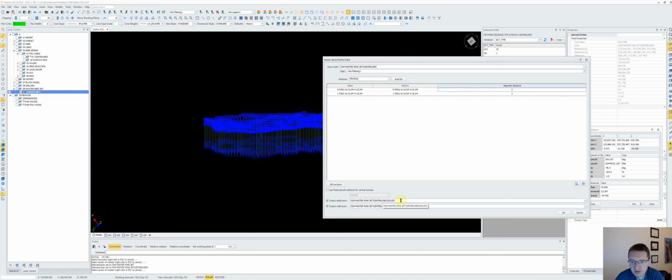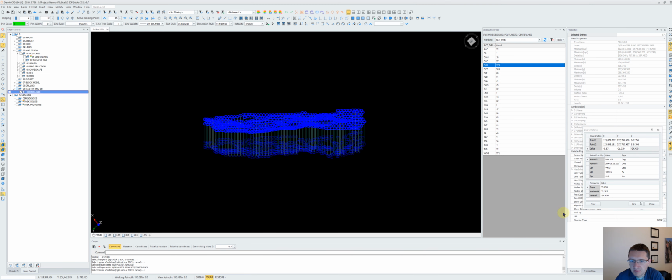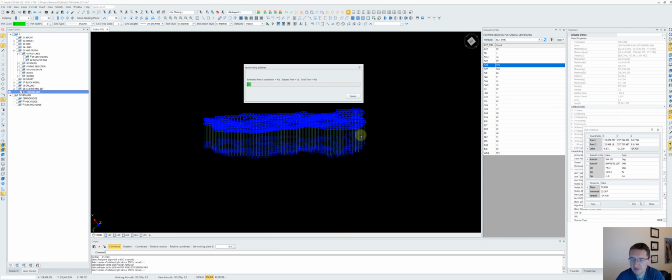And then the output is going to create solids and walls. I don't really need the walls, I just need the solids. So I'm going to hit OK. And it's going to go through and create the solids. And I'll have my master ring set. So there's a couple things there that you need to be aware of. One is attributing the center lines with the correct profile. And the second thing is creating the section profiles in draw tunnel sections. And I'll show you both of those.